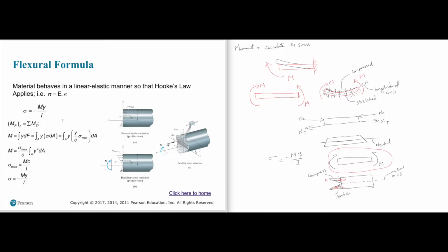So we converted the moment to an equivalent force that is being applied at a certain distance away from the neutral axis. What is the concept of moment? Isn't moment force times perpendicular distance? To get this moment, there should be a certain amount of force acting away from the neutral axis at a certain distance.